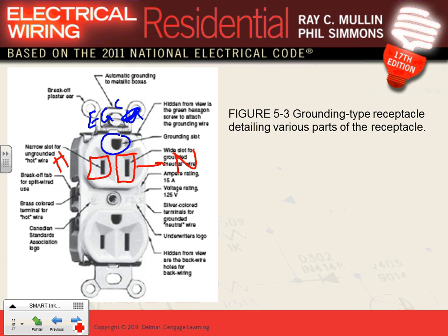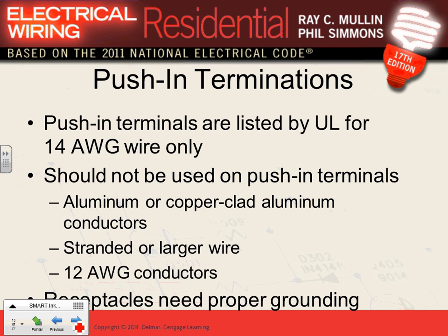The outlets. This is the most convenient outlet that we use in the US, right? You go to other countries, they use different configurations. I showed you the British, how the British use them. Very similar. You're looking at three things in almost every outlet: one hot, one neutral, grounded, and one equipment grounding conductor. NEMA has multiple configurations, guys. We'll talk about this one. I'll show you a couple of things.